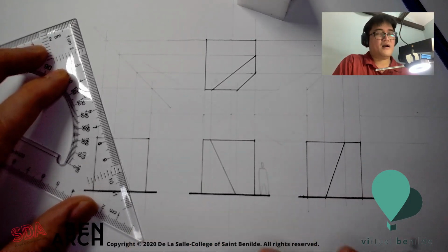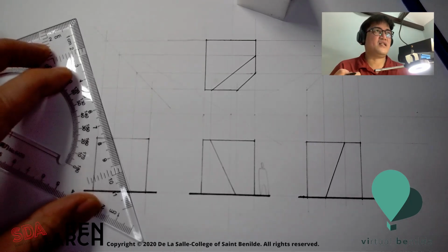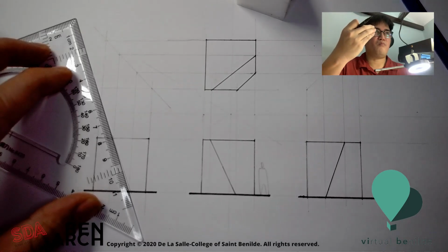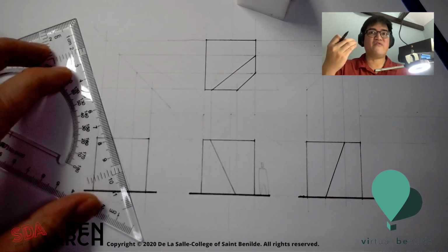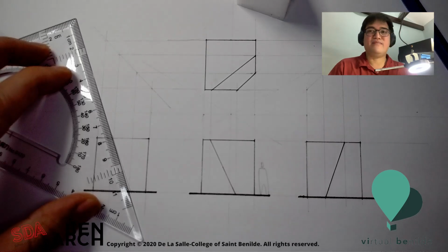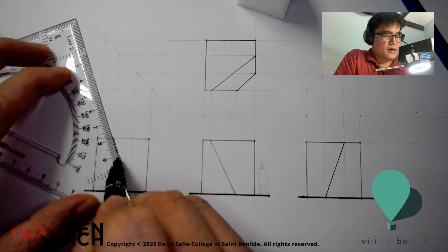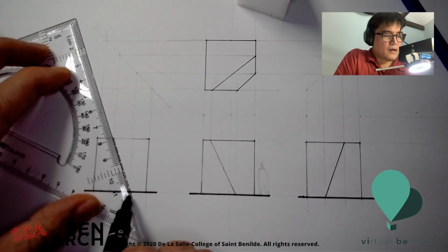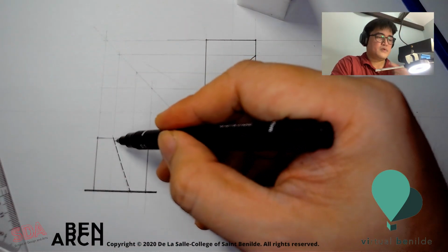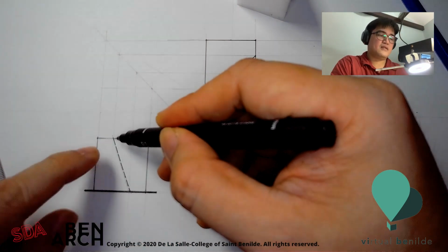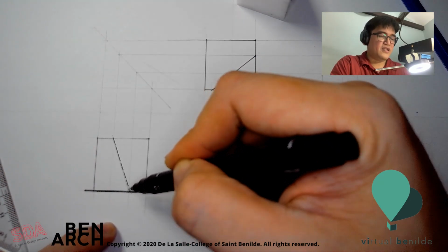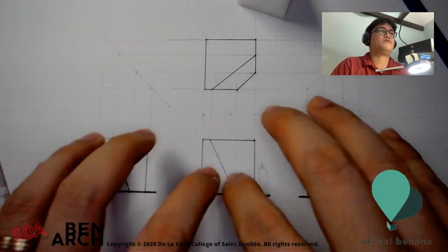Hidden lines mean that there's something that is beyond what is seen, an edge beyond, or an edge before the viewer. I'll show you what I mean when we are creating roofs. So hidden lines are these dash lines. The corners of these should be solidly meeting the line. There should not be a gap. Well, there you go. So we're almost complete.